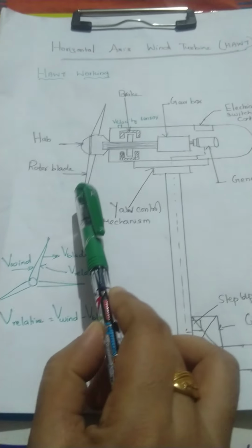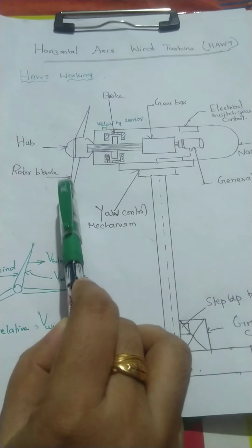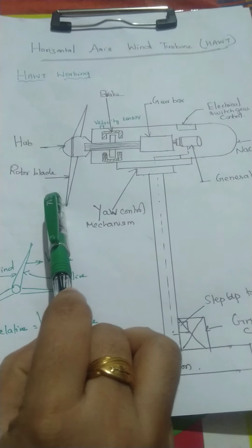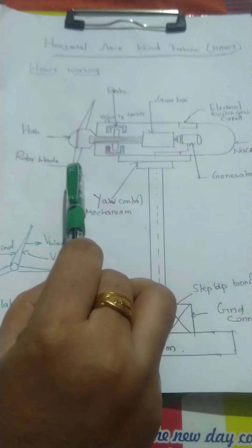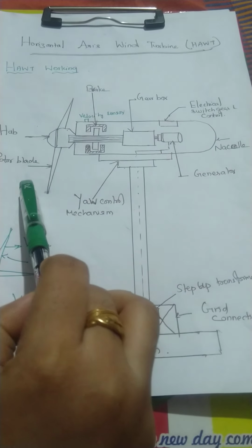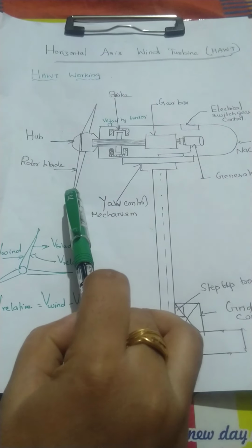Therefore, the wind turbine blade is positioned in a tilted manner in order to align with the relative wind speed. As the blade velocity increases towards the tip, the relative wind speed becomes more inclined towards the tip. This means that a continuous twist is given to the blade from the root to tip.